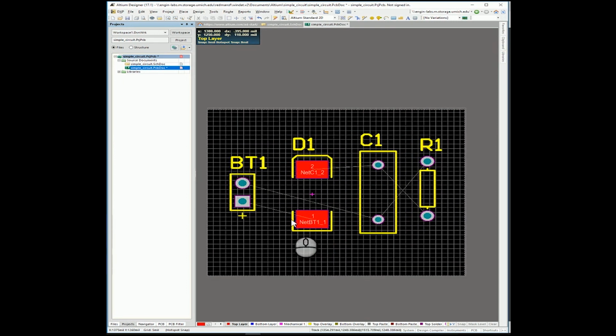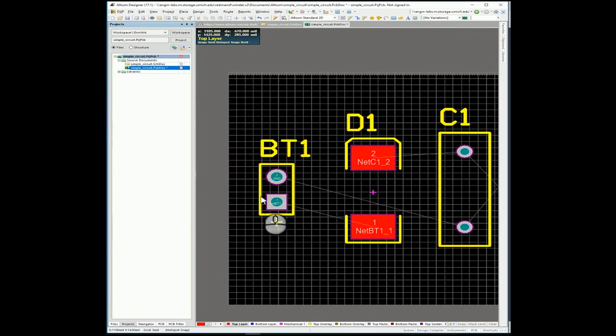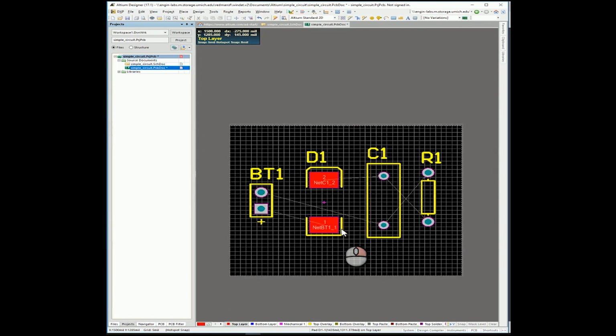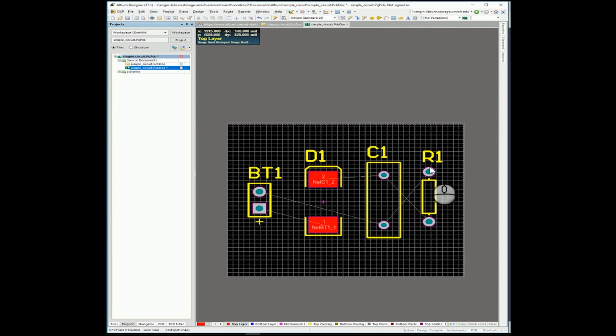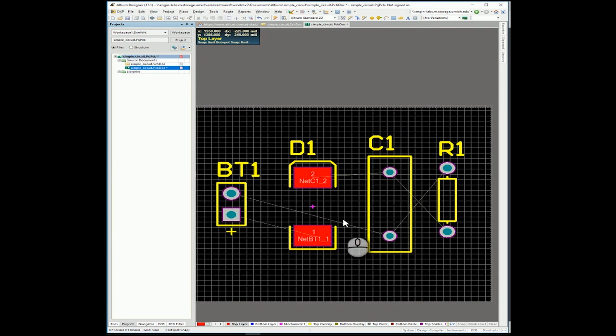And you can see these thin lines. These thin lines connect some of your components together. These lines actually are guidelines to help you understand how the board should be routed. They help you understand what ends of which components, what ports of which components are connected to other ports. So the software knows that, and it's giving you a hand here. This is useful because this allows you to plan out your routing in advance a little bit.